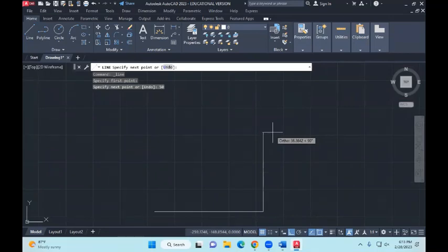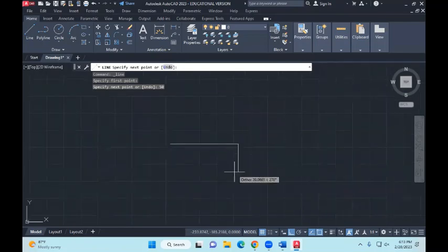Now you want to make a square that way, like at the bottom, so to speak. Right, so you just give it direction. You just point the line which way you want it to go. Obviously because it's in ortho mode, it will not go in any other angle except for 90 degrees. So you just push this line down. Without clicking, you just enter 50 again. Now it's a square.